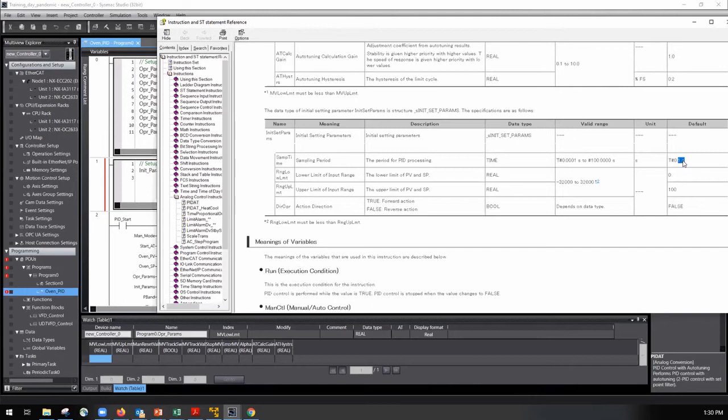I always stick with the default on this, 100 milliseconds. On the rare circumstance that you were approaching the watchdog timer on your primary periodic task, you could adjust it, but I've never ran into that issue personally. So we'll stick with the default on that.